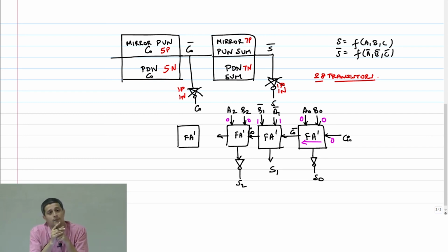And by the way, earlier when I gave you the assignment, I asked you to do the carry out circuit upsized a little bit. The reason for that is again what I just told you. The full adder is just repeated n times. So if I have all unit size devices with this load, it may not be able to drive it. So it's not that I can optimize that sizing and then figure out what the correct sizing is.